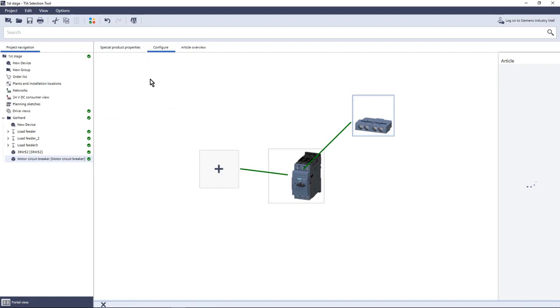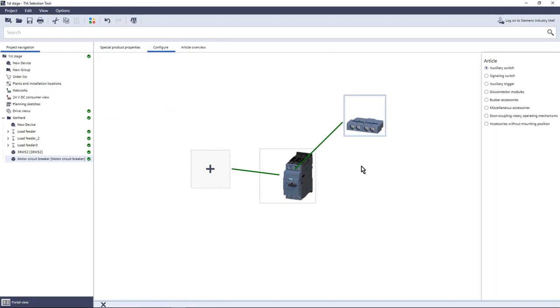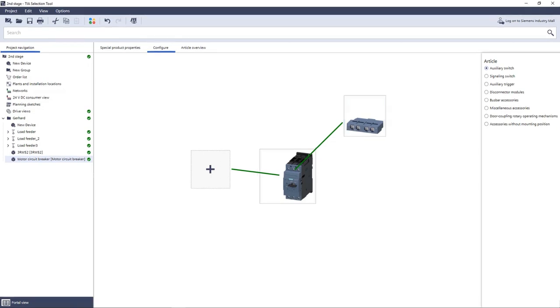Good thing that you have to realize here is if sometime you actually need an auxiliary switch, for example, you can click here in the articles that you see on my right hand side, and you can select whether you want it to be laterally mounted or front mounted. And when you click there, you get prompted in the menu to select this. Let's imagine that we need one open and one closed transfer switch. It comes here, and again it's added into the project.